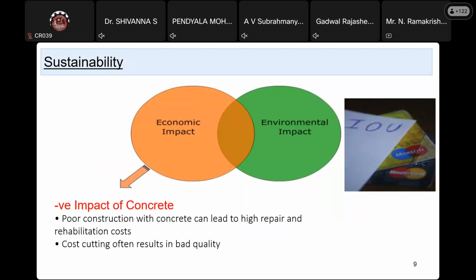Likewise, he was making a comparison of a human to concrete, like how we exhale and inhale, like how we breathe. The same thing the concrete also has through these fine pores. It is going to have air going inside. As per his deliberation, you have some 5 to 10% of unhydrated grains inside the concrete. So once this exposure to air is happening, this unhydrated cement also gets hydrated. That's the reason you get the strength.